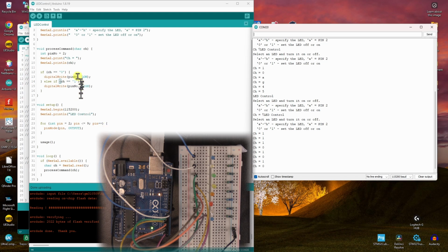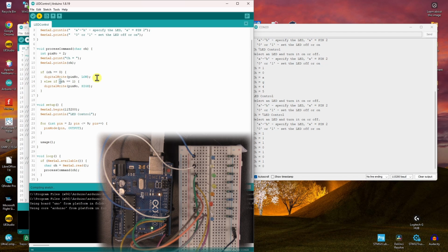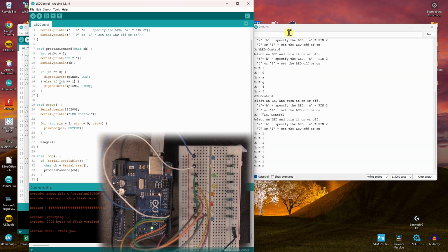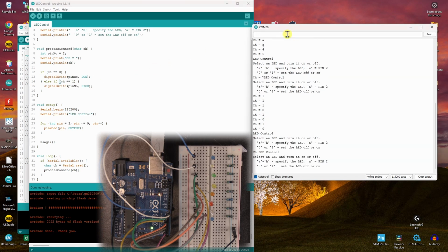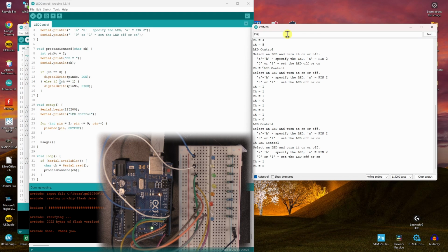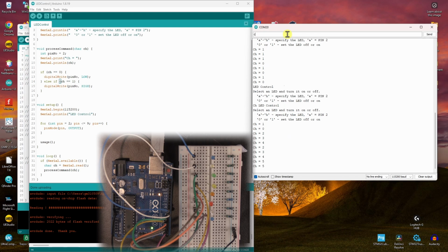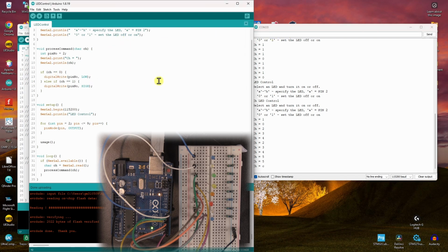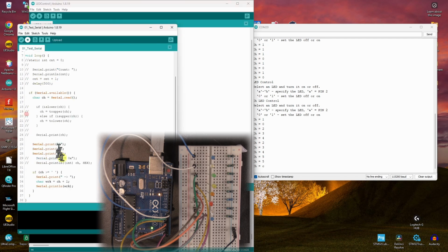I'll get that working. And just to prove my previous point, we change those back. Now it does not work anymore. 1, nothing happens. 0, nothing happens. I can type anything. Nothing happens. So no, they all don't work because we don't get numbers out of the serial read, we get characters, and the character we're getting is a 30 hexadecimal or 31, and that from this program.